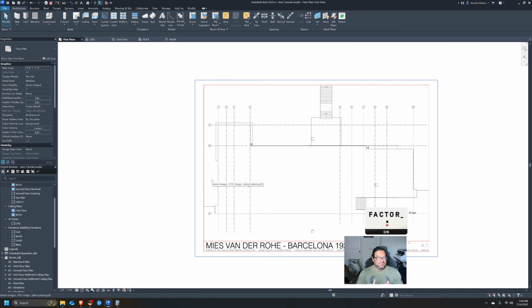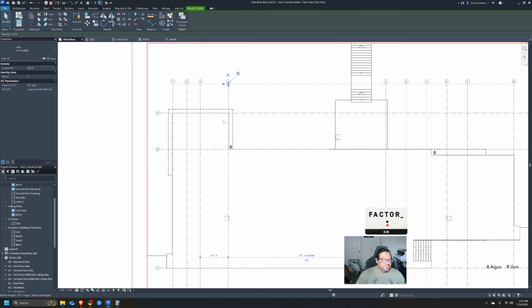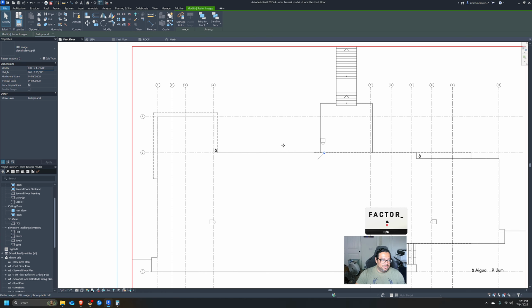In Revit, we went over how to set up and bring in an import, whether it be DWG, CAD, PDFs, images, it doesn't matter. We went over how to scale the image to match any scale that you're going to do. Now we went over how to briefly do grid lines, and this probably doesn't matter, but it was good to explain it. And we went over how to briefly do a floor.